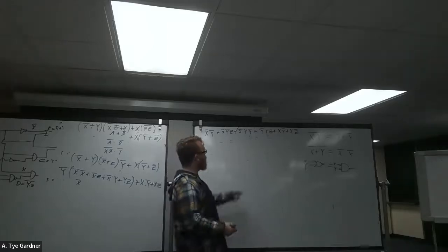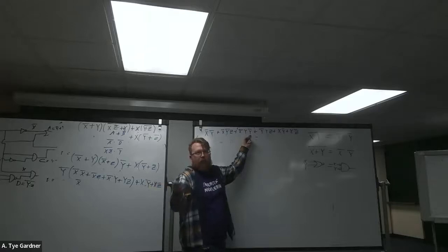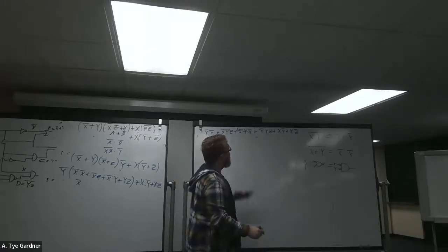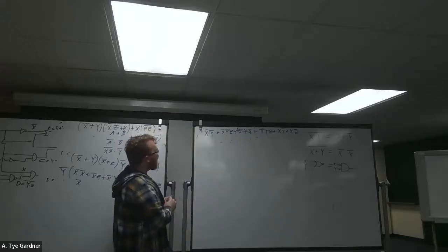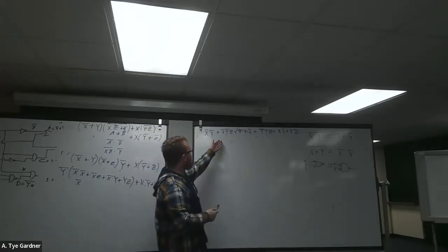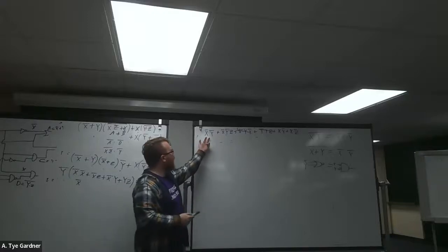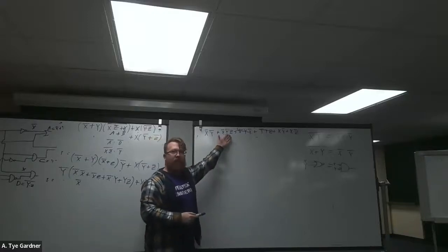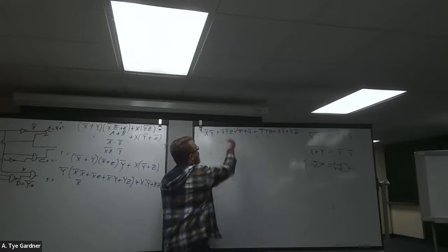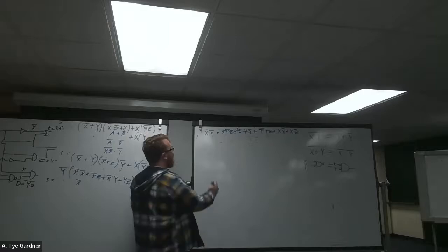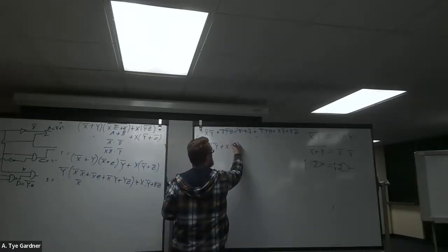All right, let's start looking for things that are easy, right? And the easiest one is anytime I have Y and not Y, it goes away because it's just 0 and or with 0. So that goes away. Y and not Y goes away. Great. I would like to find, if I could, something that was like not X and not Y. See how I have this term, and then and that, and it doesn't care about that Z, so this whole term is redundant. Goes away.